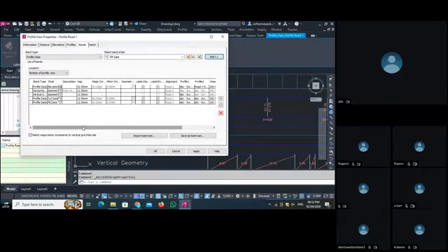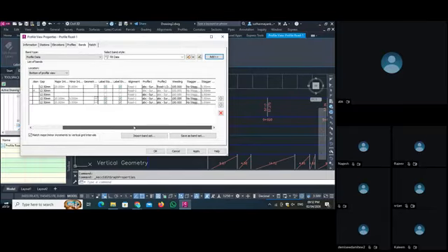Now, in the cut and fill data, the last two rows, I have to change something here. I want to show the cutting. For cutting, profile one is my existing profile and profile two will be my road one profile. So they differentiate my existing profile from the design profile.